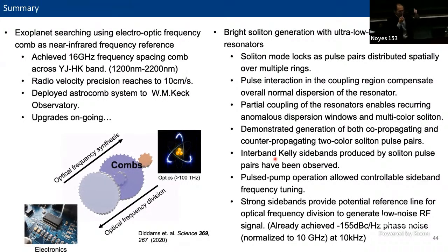And from the other direction, from optics to electronics, I go through this very quickly, but hopefully you can notice that the soliton frequency comb I discussed in the second part is a phase-locked optical frequency comb. If you take the beat note between all the comb lines, because their phases are the same, the beat note will have a single tone, a clean, strong radio frequency signal. By taking the beat note of the optical frequency comb, you can down convert the stability of the optical domain to the radio frequency domain.